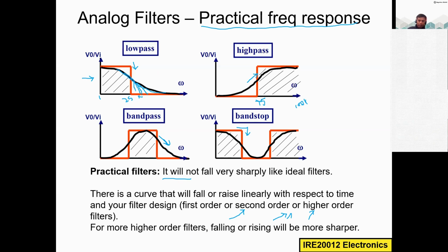And then the fourth order may be here, and then the fifth order almost here. So I cannot go more than that. There may be some limitations, because it also depends upon the R and C values when you design the filters. So there is always a limitation in practical filter design. We will see them now.